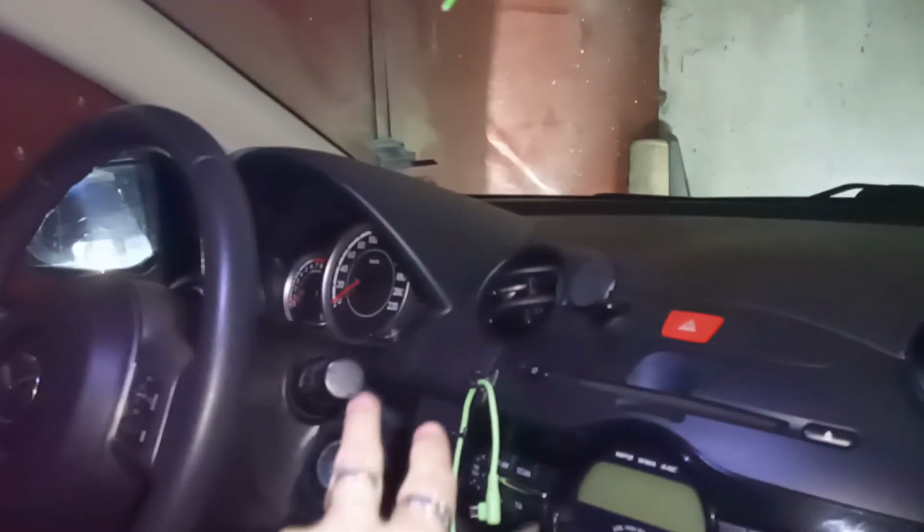And now when they actually go off, I'll even lock the car. Locking the car doesn't activate anything, but then unlocking the car, because it thinks it's pitch black outside, it actually turns on the headlights. And keep in mind, these are only headlights without TNS. The idea is not to beep when you open your door, because otherwise it's beeping. If you open the driver's side door and you have TNS on, it will beep. This will not beep, and in a bit this will go off.